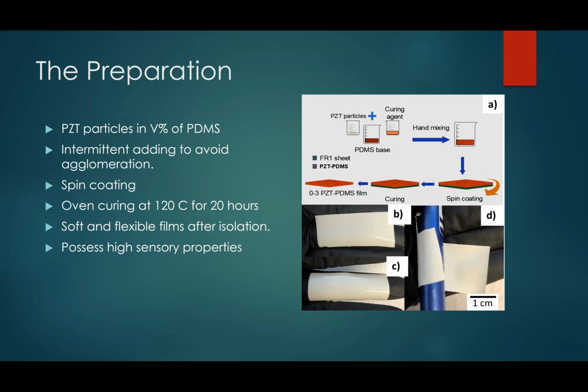So we wanted our own piezoelectric substrate that has flexibility, but at the same time has a good piezoelectric charge constant. So we made our own piezoelectric composite substrate by mixing PZT with PDMS.